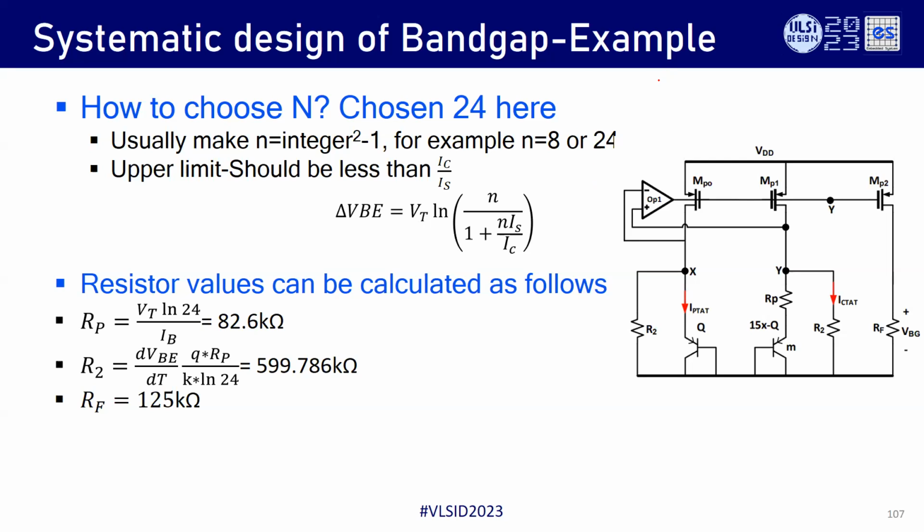If we take very high N, the amount of op-amp offset amplified at the output will be decreased. So higher N is always good. In fact, I have seen people at Qualcomm use N equal to 300 for low noise bandgaps, I mean, low noise VCOs and all.